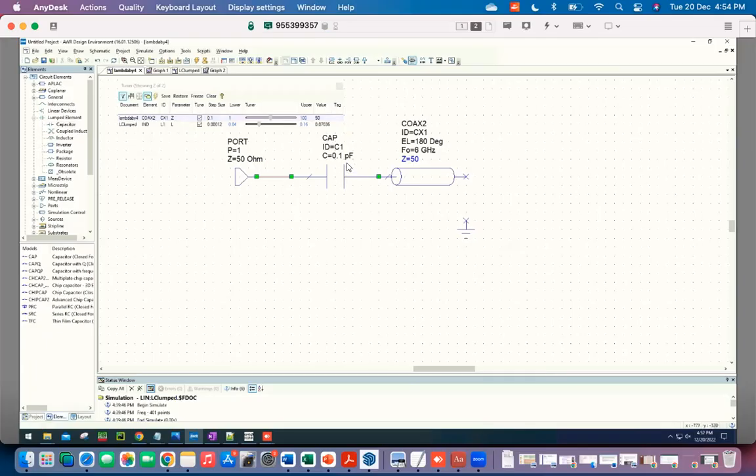So how does that work? The smaller the capacitance, the larger the impedance, which means more strongly reflecting. So if you imagine this goes to the limit of infinity, then this becomes a perfect open, right? If this is very large, then it directly connects to 50 ohms. So anything in between, you get partial reflection and partial transmission through this. So this is now able to control how much of the energy that might be stored in the resonator can leak out into this 50 ohm environment.